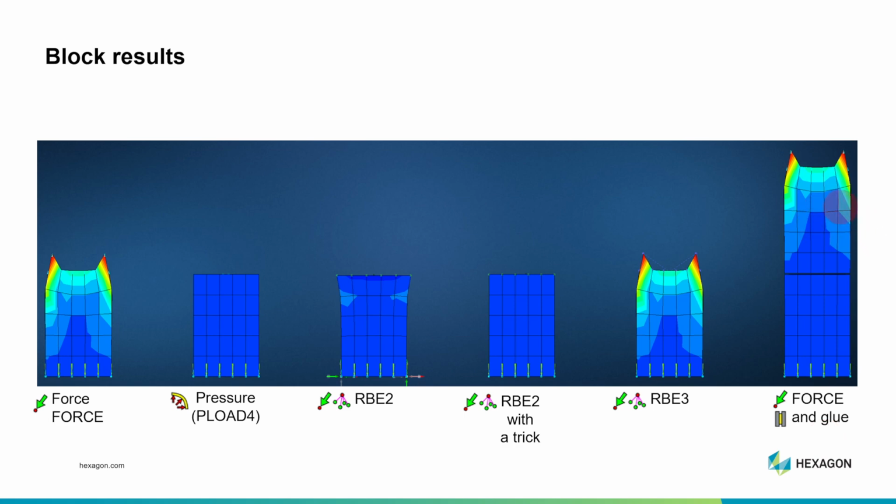Having a new part added, applying load to the top of that, and then letting the load be transmitted between the new part and the part that we're originally wanting to study. This is a great example of St. Venant's principle. St. Venant's principle simply says that the farther that you get from the point of application of a load, the less it matters exactly how it's applied.